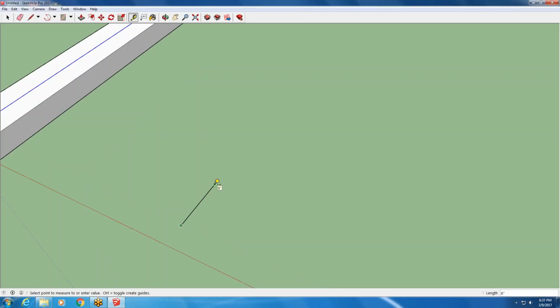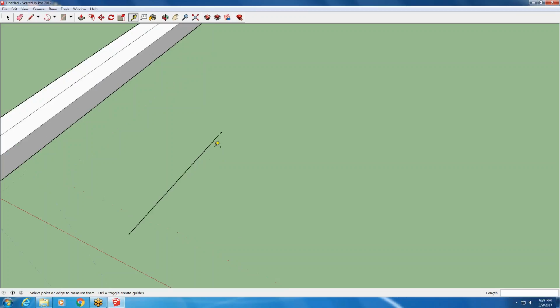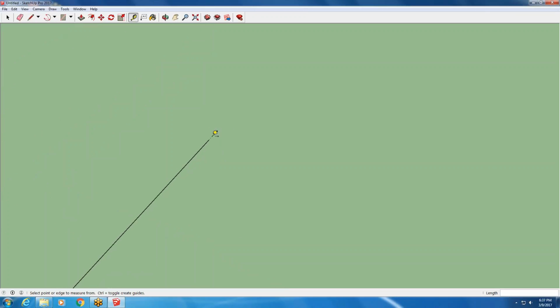It's just going to be 6 because it chooses the last value after the dash. So as precise as you think you might be being, you're actually throwing SketchUp off. It just wants 1 foot 6 inches, no dash, and then it should draw what we want it to draw. Yes, I just overmeasured. See, it told me I overmeasured that much.